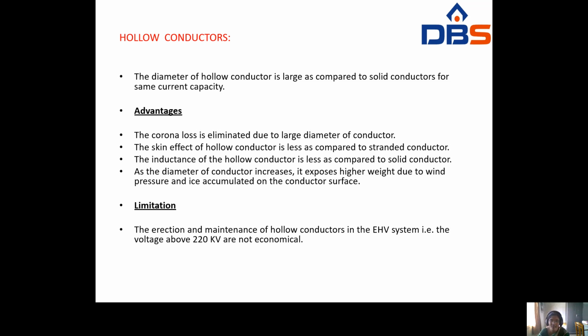What are the advantages of the hollow conductors? The corona loss is eliminated due to the large diameter of the conductor. The skin effect of the hollow conductor is also less as compared to the standard conductor. The inductance of the hollow conductor is also less as compared to the solid conductor.